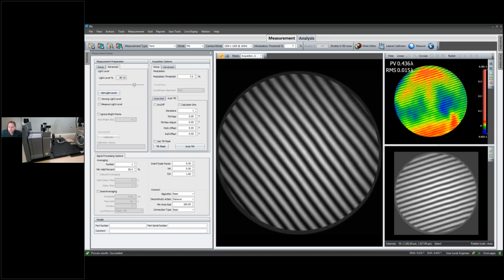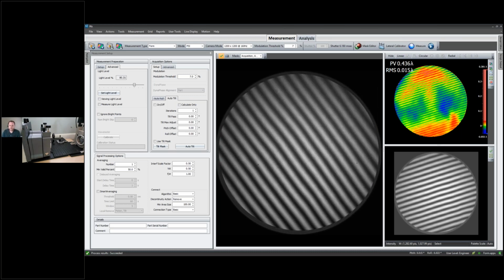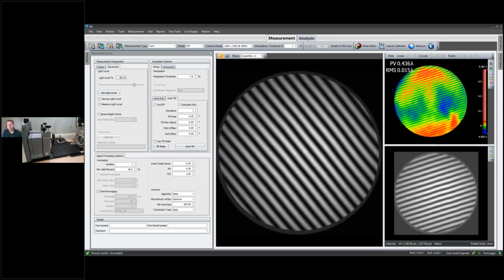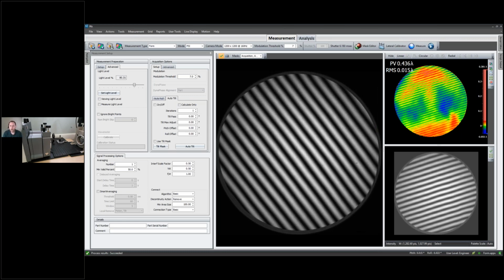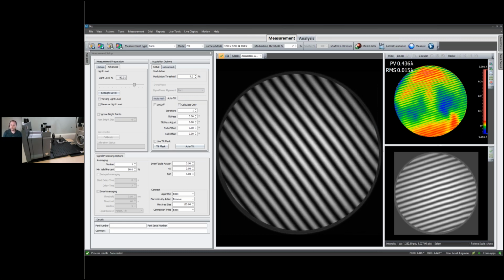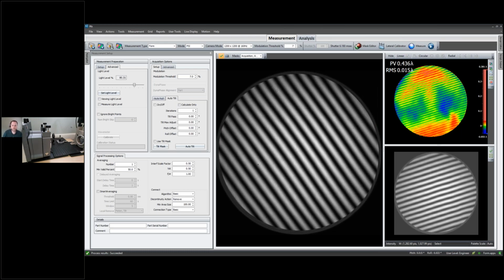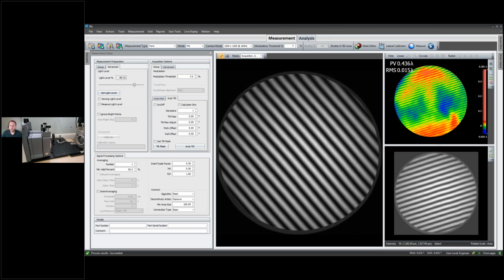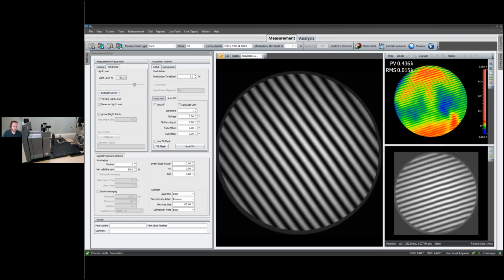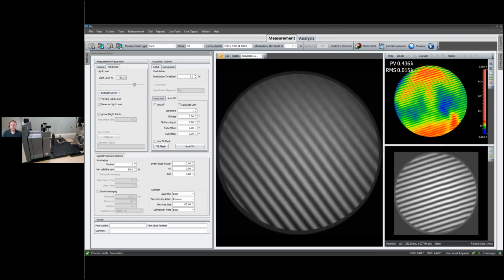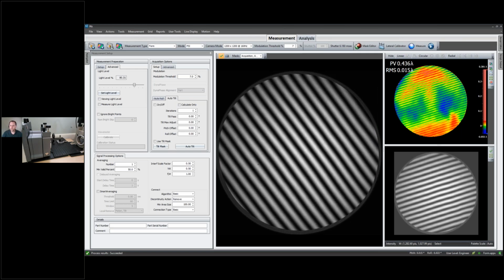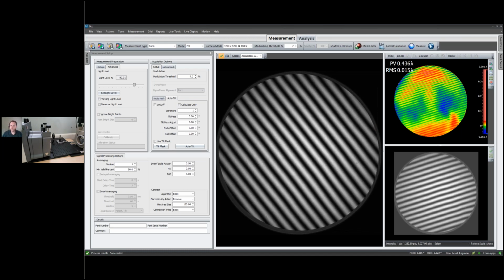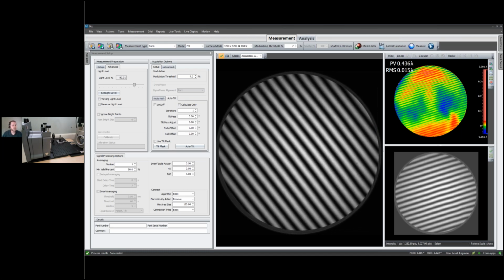This method also can be pretty difficult depending on the test size. So if you have a very large cavity or a very long cavity, that beam and that need to bridge the gap becomes really difficult. And on the other hand, if you have a small test part, whatever you end up bridging the gap between the interferometer and part with is just going to be too lightweight to efficiently couple that cavity and reduce the vibration. And in either case, you absolutely run the risk of actually damaging your parts using this technique.